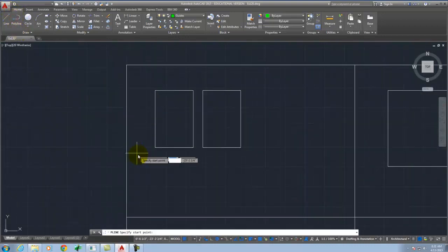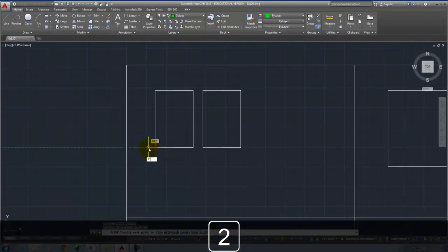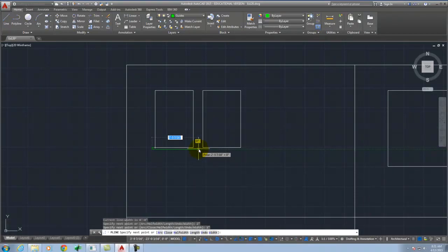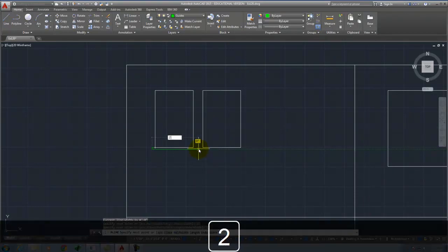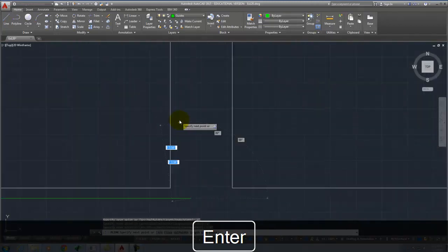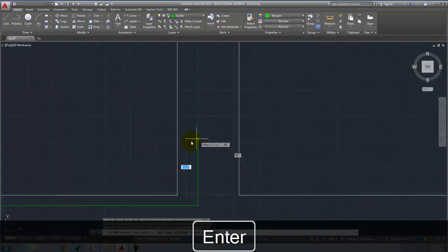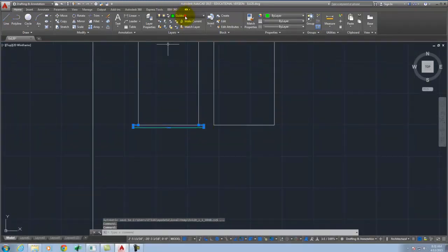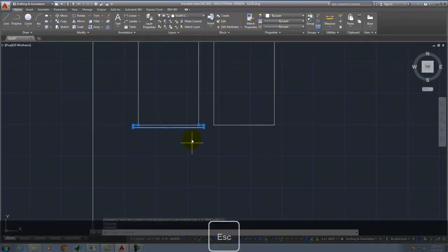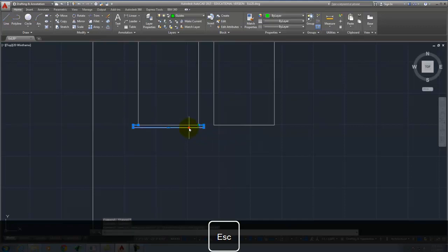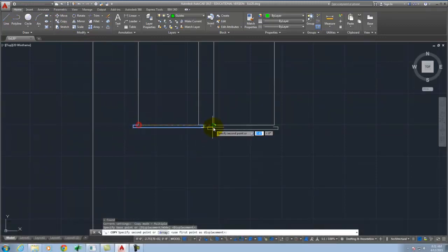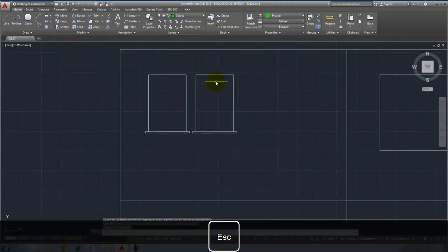I'll use the polyline tool in this case. Let me draw a window sill. So let's come over here, I don't know, 2 inches. Go down. Come across here. I don't even remember what these windows were. They're probably something like that. All right, there's a little windowsill that goes below the window. Let's put it on the south elevation layer. And let's go ahead and take this and we'll copy it. I can use the copy command right here too. And we'll copy from here to over there. Just trying to give ourselves a little bit of definition.